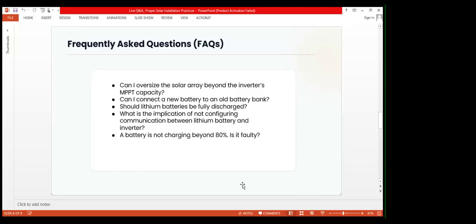It may look like you still have a lot of energy, because if you go below that, it may shut down and not wake up. If your inverter does not have an auto wake up function to start when the grid comes or when solar comes on, you'll be in trouble looking for an external power supply to boost charge the battery. So that's just the answer to that.